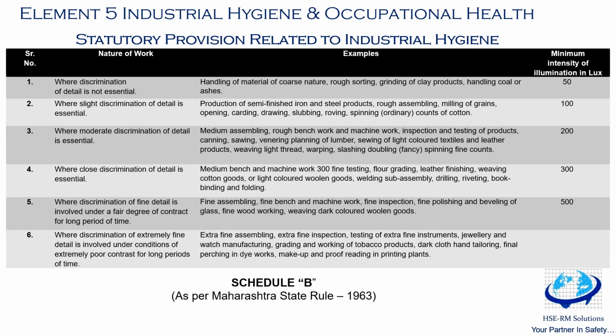If you require medium level, where you have to observe whether this is happening correctly or not, there 200 lux. Where you are going for the testing phase, there 300. Where you are going for extremely fine reading, you have to see, there 500 lux and above. So correct, this is all about the lighting or the illumination part.